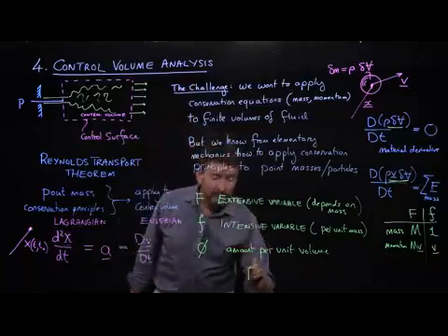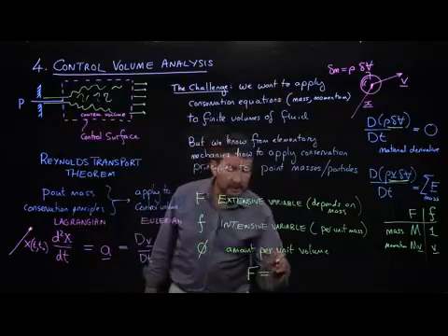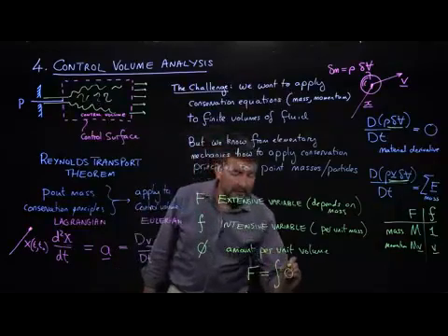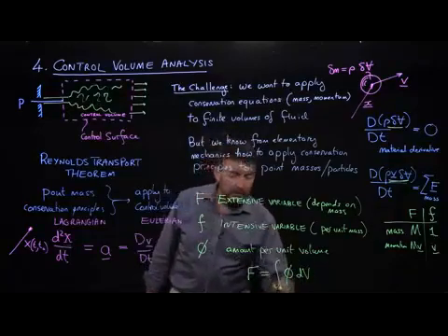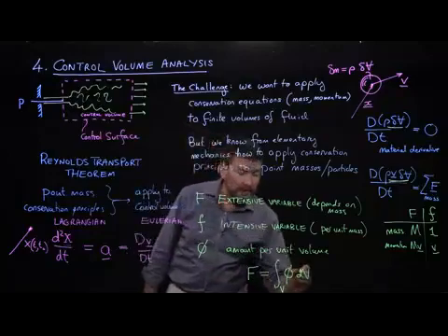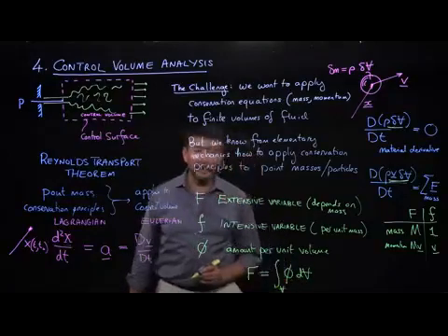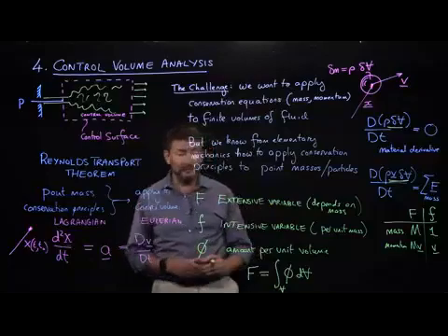And the way to understand the conversion between these is to recognize that the extensive quantity is nothing but the integral of phi dV over our volume. So we'll always write a volume integral like this, and we'll use a bar through the V to recognize the difference between volume and velocity, because that can be confusing.